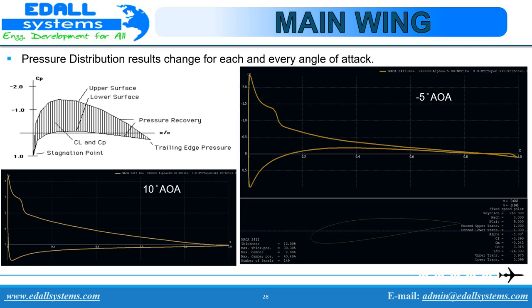The pressure at the trailing edge is related to the airfoil thickness and the shape near the trailing edge. For thick airfoils, the pressure here is slightly positive. The velocity is a bit less than the free stream velocity. For infinitely thin sections, the coefficient of pressure is 0 at the trailing edge. Large positive values of coefficient of pressure at the trailing edge imply a more severe adverse pressure gradient.